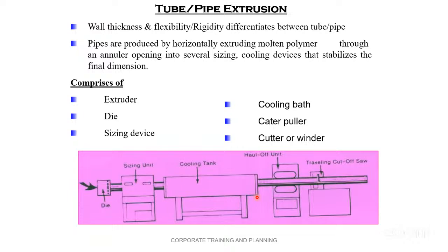Sir, we are doing compounding of engineering material like nylon and some PP, ABS also. But we are using the same cooling tank, six meter length only, for all the material. Depending upon the material, we are keeping it. Some material are kept for a longer distance in the water in the cooling tank, and some material like nylon and all that are kept only for 1 or 2 meter in the cooling tank.